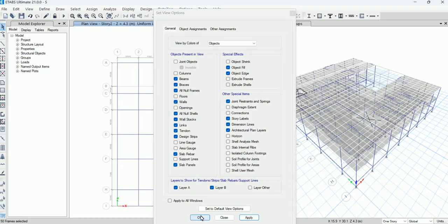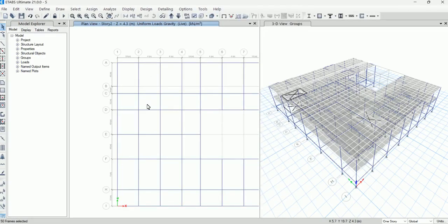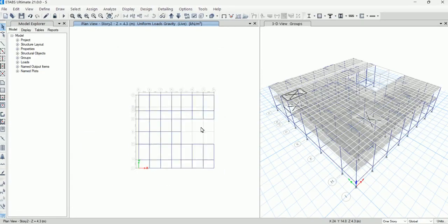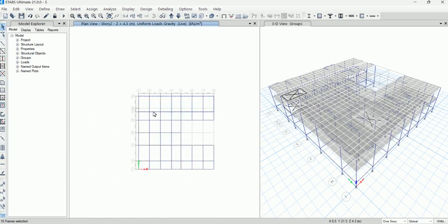Okay, so now I can select all these walls like this. Only your frame will be selected. Just deselect this one, and from here you can clear your selection, because your group 1 was already defined. Just select this, and for the beam, apply load here, this one. Come out and apply your load here, and for the load up to this frame, this edge.